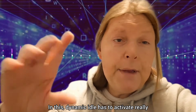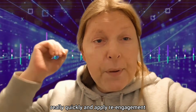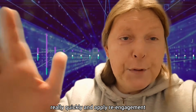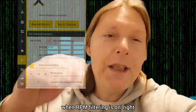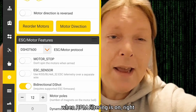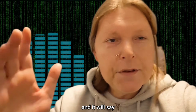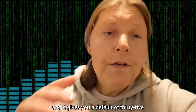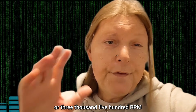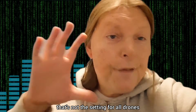In this, dynamic idle has to activate really quickly and apply re-engagement. Just quickly to mention that obviously dynamic idle is set when RPM filtering is on, right? And that's what most people have nowadays. So you'll select a preset and it will say, do you want RPM filtering? RPM filtering comes on and it gives you a default of 35 or 3500 RPM. The thing is that that's not the setting for all drones.